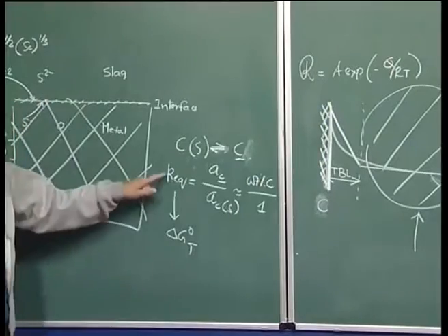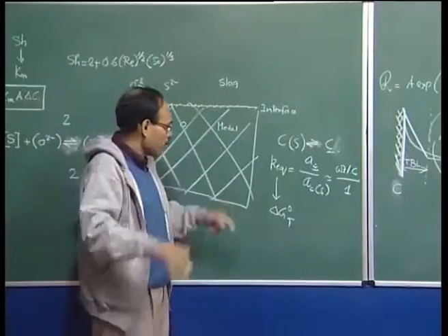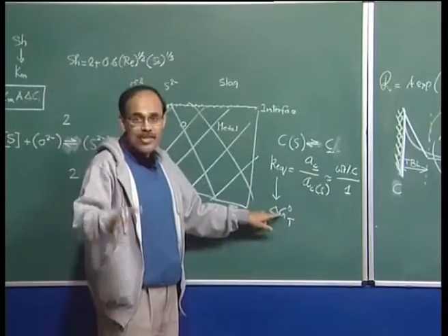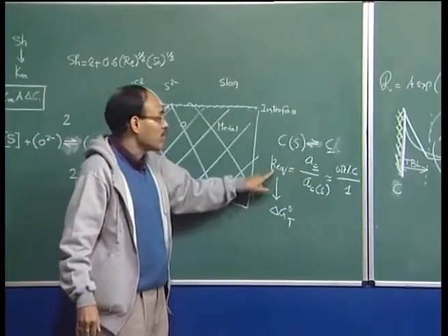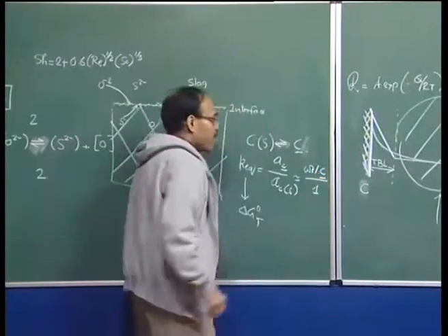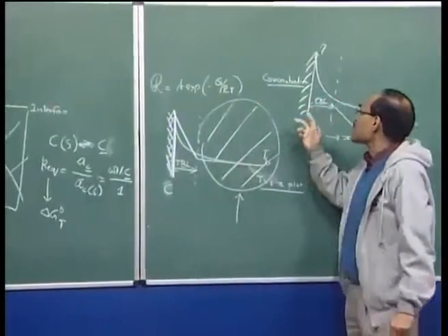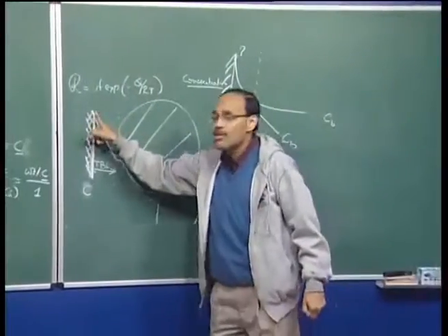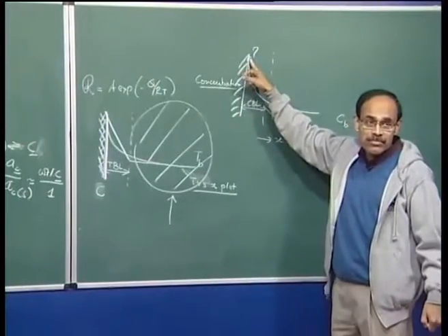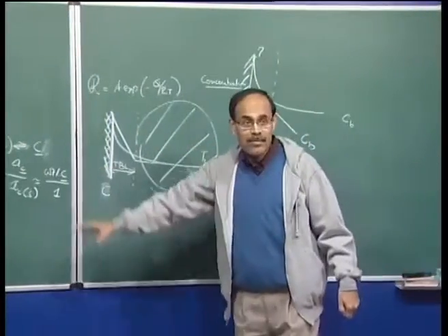So, if you know delta G naught, because delta G naught values will be known maybe from Ellingham diagram type of diagrams or from a thermodynamic data book, knowing the temperature, I will be able to calculate delta G naught is equal to minus RT ln K. K equilibrium will be calculated, and this weight percentage of carbon at the interface will be known to us. So, while in the case of heat transfer we determine the surface temperature by using some kind of a pyrometer or thermometric devices, in the case of mass transfer, often the interfacial concentration is going to be determined through thermodynamic considerations.